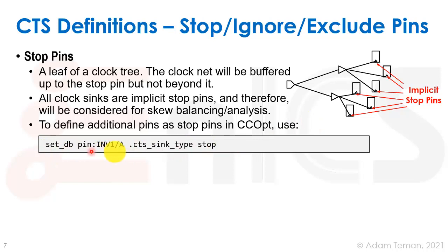And by that, build your definitions for your clock tree synthesis for it. It's really important, or else you're going to run into all kinds of hold violations, especially at later stages, or a really bad and ugly clock tree. So I'm not going to go too deep into it during this course, how to build clock trees for specific designs, because it really does change for each design, and it gets pretty complex when you go down the road.